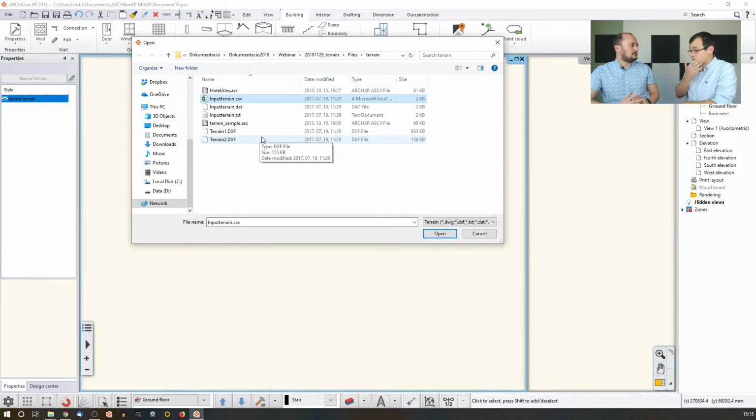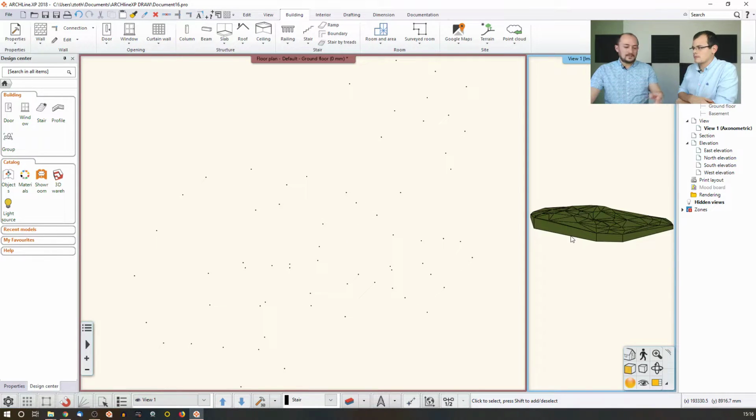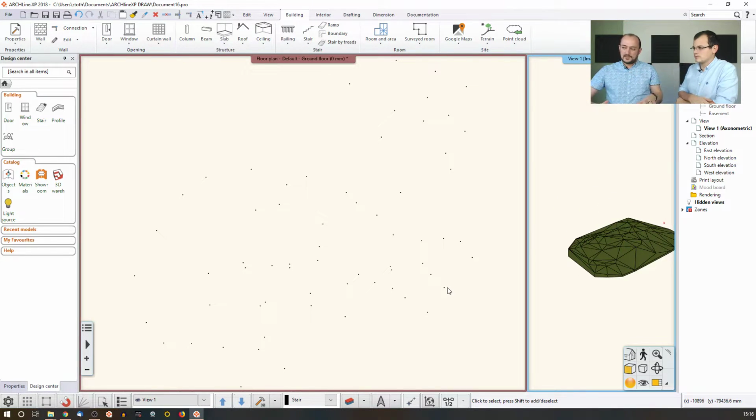Yes, they could be total stations or any kind of device which is able to get you three-dimensional data in numerical format. We'll discuss this later on. And so it's kind of a point cloud, just treated as a terrain. Yes. So we will load this information, and again, the software creates this terrain, and I can visualize it in 3D, and I will get a nice result with that data, in that specific resolution in which it was measured. So that's what I see then. At the same time, again, I can add the building. We will cover that soon.